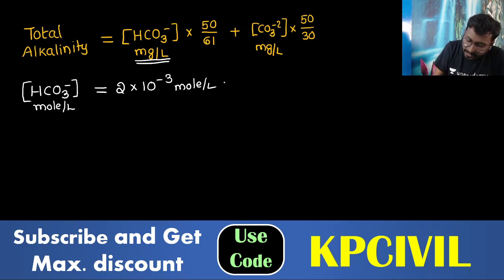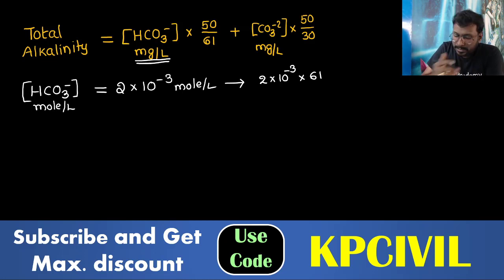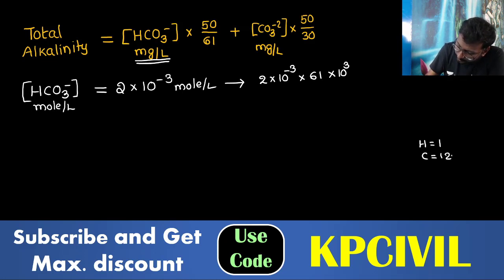So now we are converting to mg per liter. 2 into 10 power minus 3, into the molecular weight of HCO3 minus, 61, into 1000. HCO3 minus: hydrogen 1, carbon 12, 3 oxygens, 3 into 16, total 61.